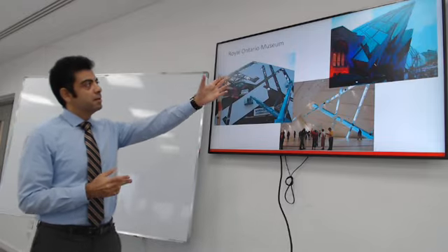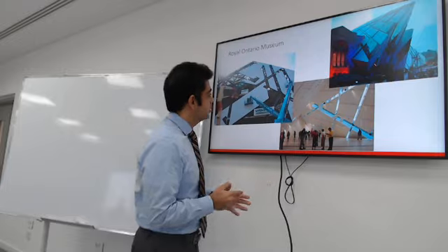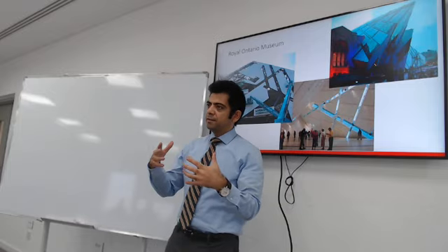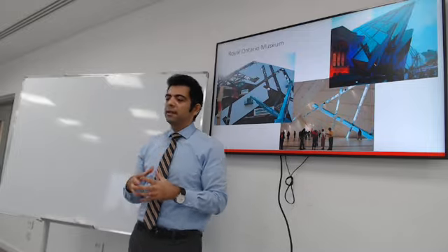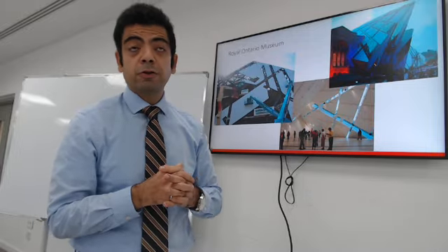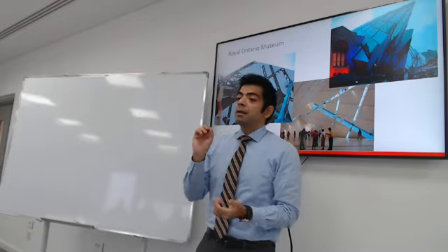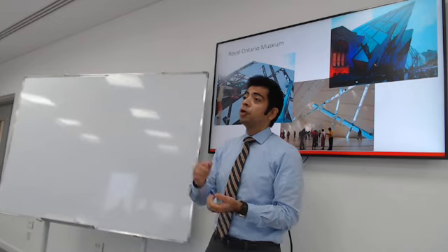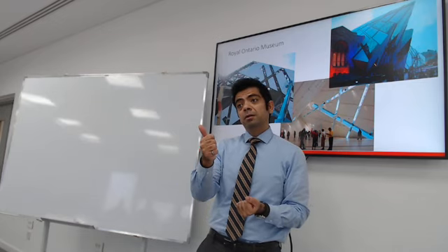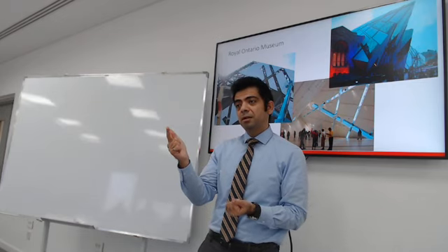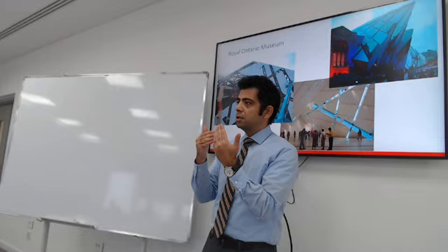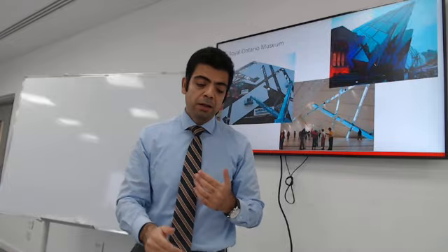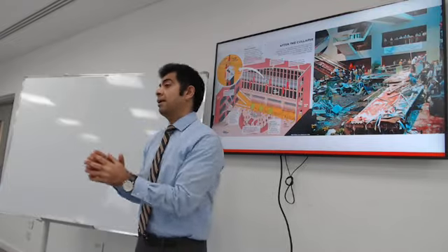And it becomes these very interesting, complex shapes, because of the flexibility of steel, you can create interesting details and work around existing structures. Having said that, the role of connection design could make or break the building. You could have a good beam design and good column design, but if the connection is not very good, the failure will happen at the connection. And the consequences could be catastrophic.